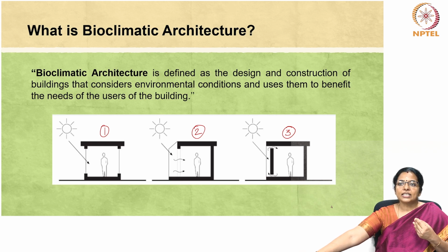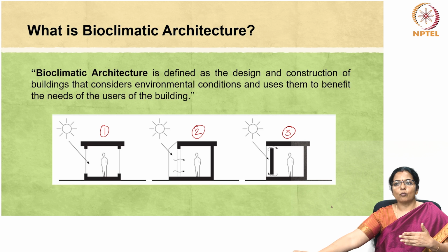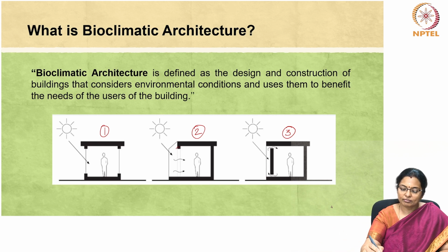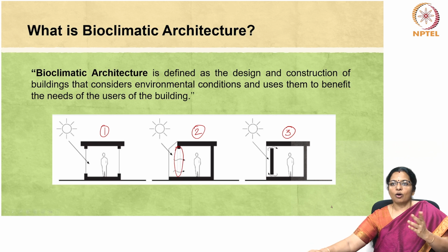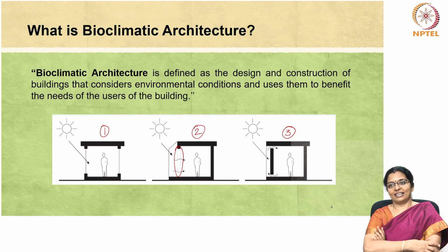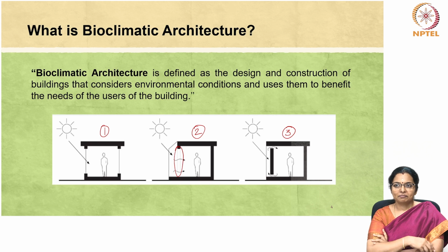Instead of sunbeams coming right inside the building, indirect gain is when the sunlight warms up a particular surface, say like a wall or something there. What those somethings are, we will see later during the course. So it's like a sunny sidewalk which warms your feet even after you step off it.